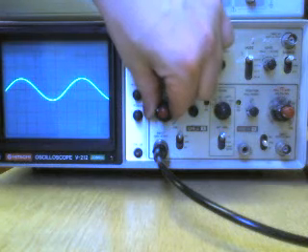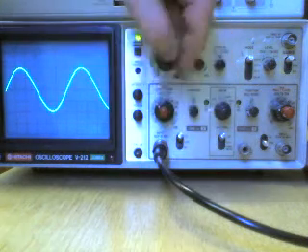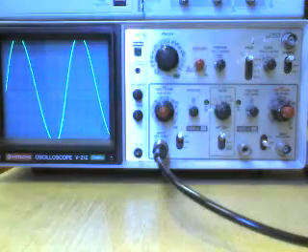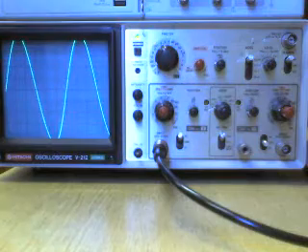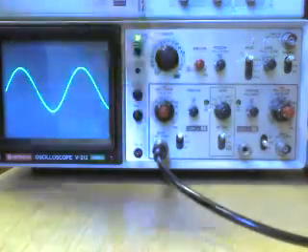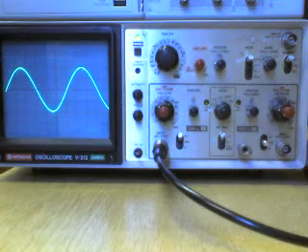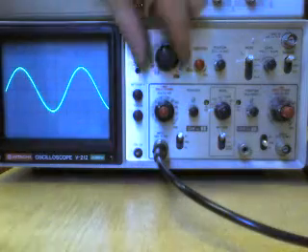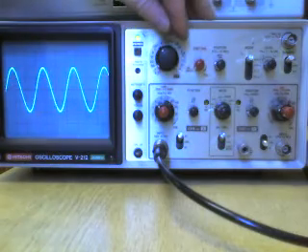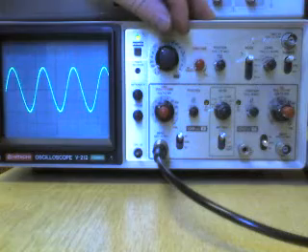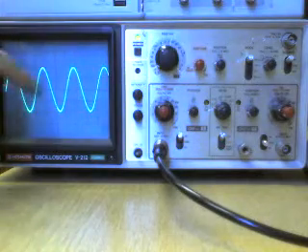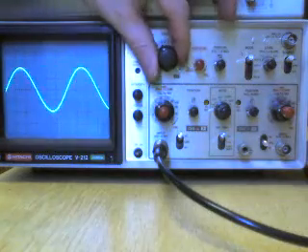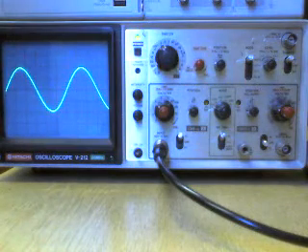It may seem strange that I'm increasing, but I'm actually decreasing to half a volt per division, or 0.2 volts. 0.2 volts, it goes off the screen. 0.5 volts per division, it's actually on the screen, so that's as large a signal as we can get on the screen. Same for time. Got quite a few cycles on the screen, but I only need 1 cycle. Go the opposite way, it's off the screen, so somewhere around there is quite nice.